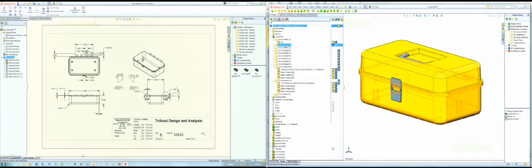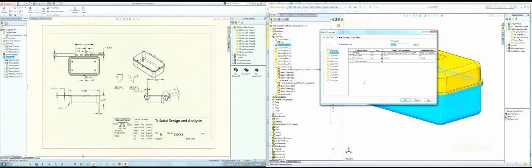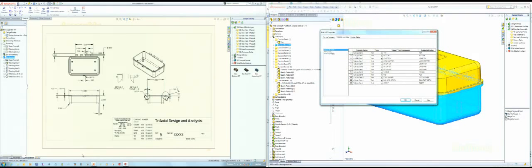Okay, then the secret is we went in here to each of the cut list items, and we went to the properties of that cut list item. Now this is a little bit different. This is talking about custom properties, but it's within the cut list item, so it allows you to edit them slightly differently. We can go to the properties summary tab, and these are the custom properties that I have assigned to all the different cut list items. Let's say description is the one we want. It's showing you all the cut list items at the same time and all the descriptions at the same time. So this is just a different way to rearrange the custom properties within this file.